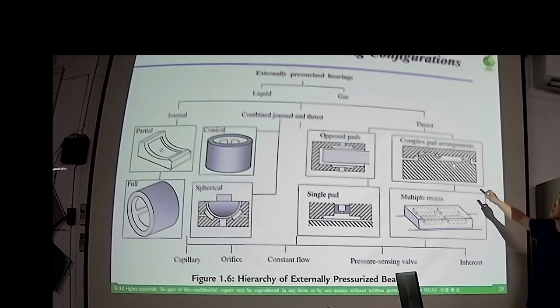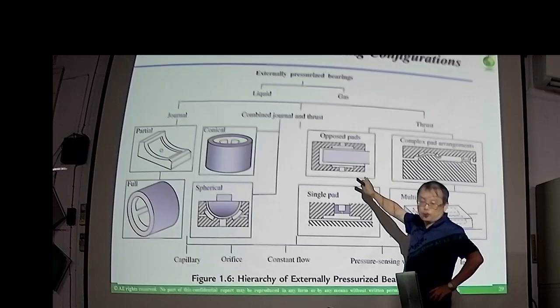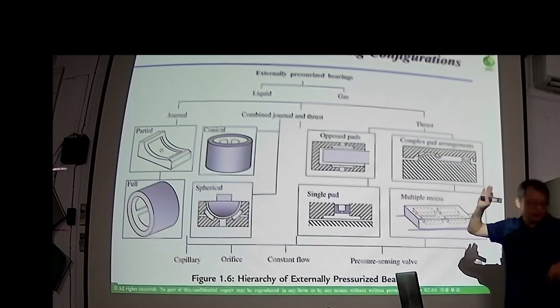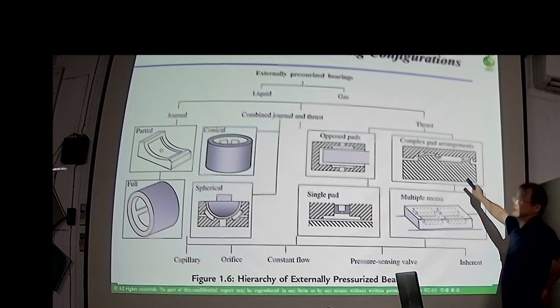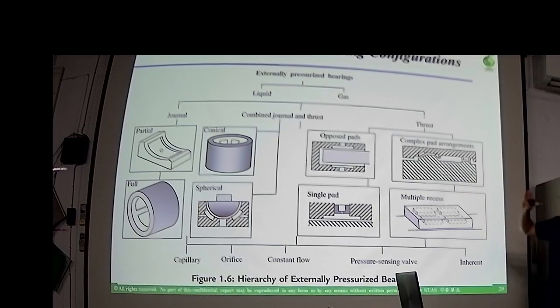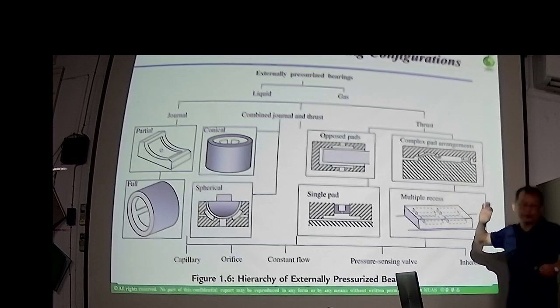Okay, so here is the slide table for the grinding machine. And for the opposite side, the slide table is usually used in the milling machine and turning machine. For the grinding machine, the cutting force is very small, so you can use the open guideway system.